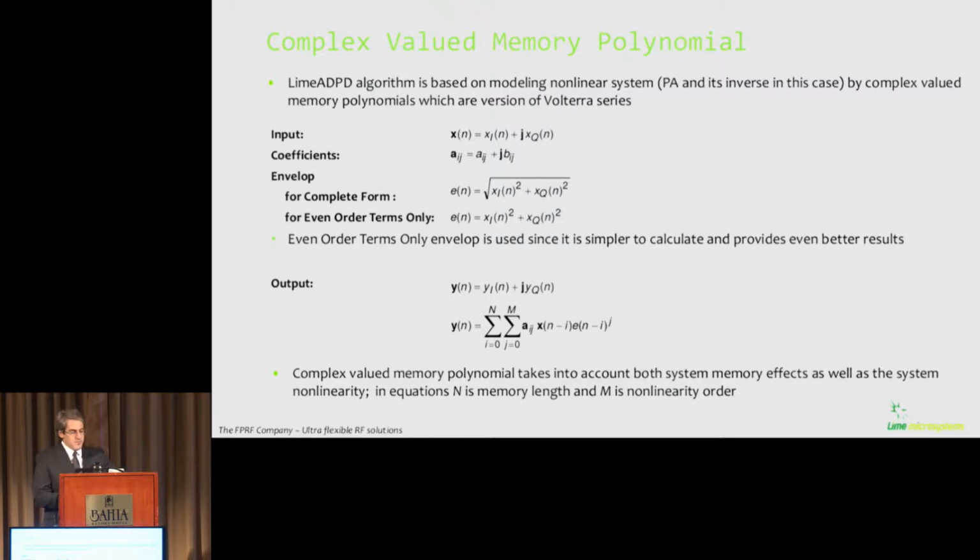Our algorithm, Lime ADPD, is based on modeling of a nonlinear system, such as a power amplifier, and its inverse. This is modeled by complex valued memory polynomials, which are in fact a truncated version of the Volterra series. For a given complex input, x, we obtain a complex valued memory polynomial output, which is given by an equation presented in the slide.